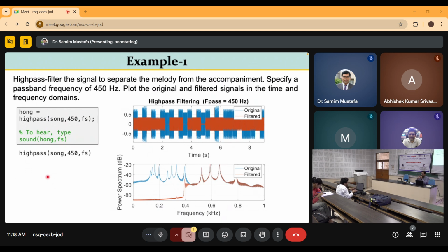Because first frequency is the lowest, then second will be slightly higher, and so on. So a bridge has a lot of frequencies, as you know. We can only measure some of them because we can excite the entire bridge only to a certain extent. So probably 5 or 6 modes initially we can measure from the experiment.